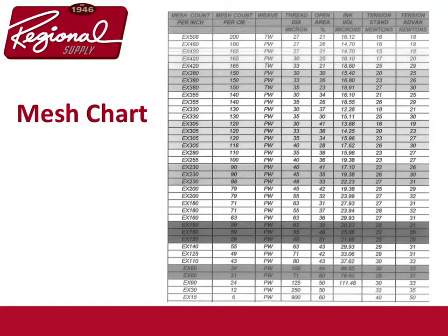Years ago, when screen printing was just at its novelty, when you would order a mesh count, there was only one mesh, like a 110 or 230, 150. Today, years later, they make very different variables in the mesh counts. 230 comes in 2 different thread diameters, 150 comes in 2 different thread diameters, and so on. And this is important because each thread diameter will give you a certain ink deposit that you're looking for, and some will maintain fine detail better than other thread diameters.